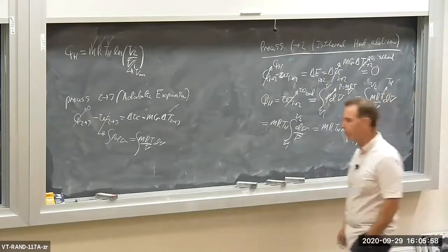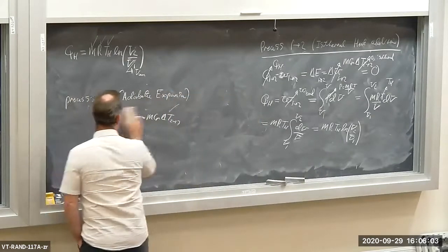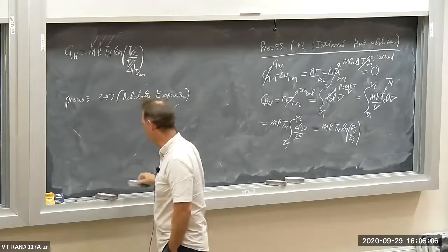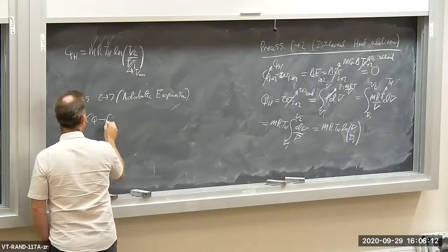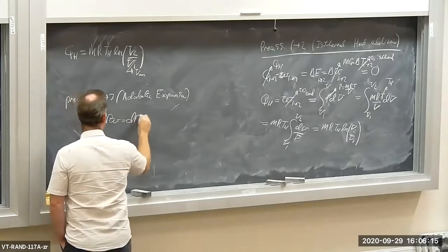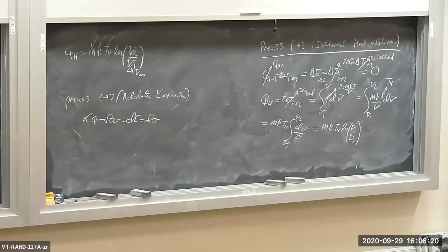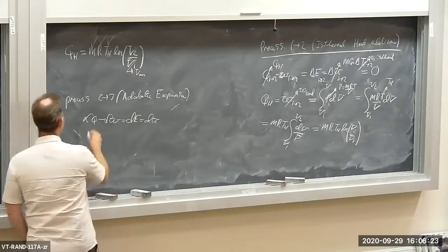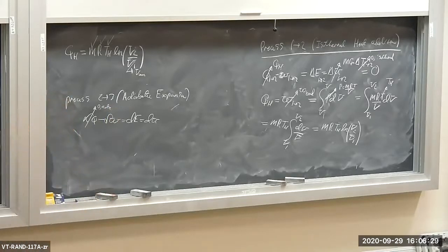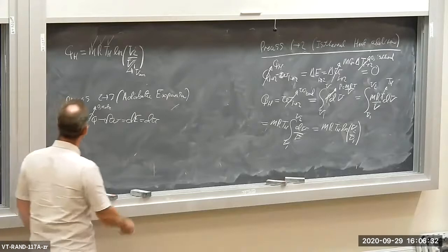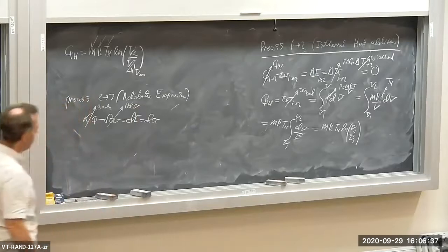We're going to write another version of the energy balance. I'm going to write the differential version of the energy balance, differential process. Del Q minus del W is equal to dE, which is equal to dU. That's the differential version of the energy balance. It's adiabatic, so that goes away. And of course, the work is boundary work, so this is P dV. That's the boundary work.